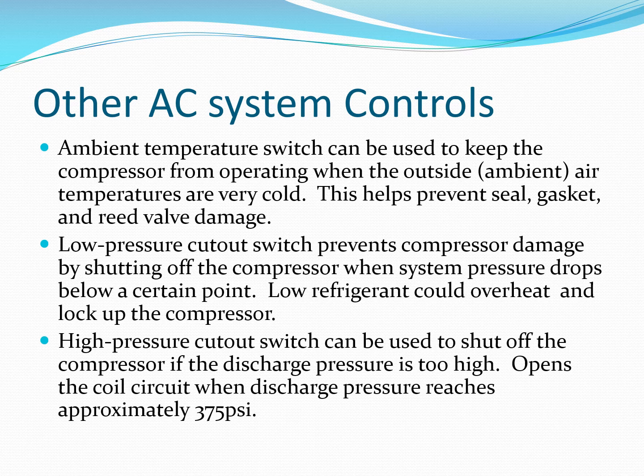If the compressor pressure is too high, again, we could burn up the compressor due to too high head pressures, and therefore we want to shut off the compressor if that pressure gets too high. Another example of this is the DIYer. We can buy this refrigerant in small quantities almost anywhere these days, whether it be Walmart or Blue Stem or the parts store.